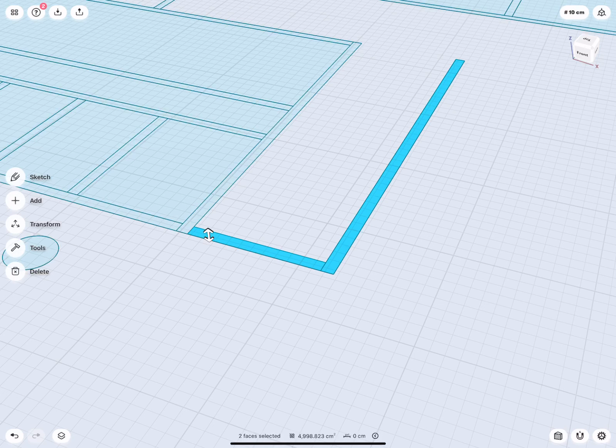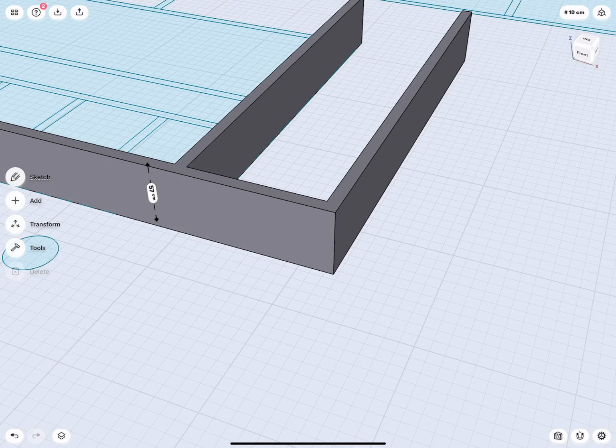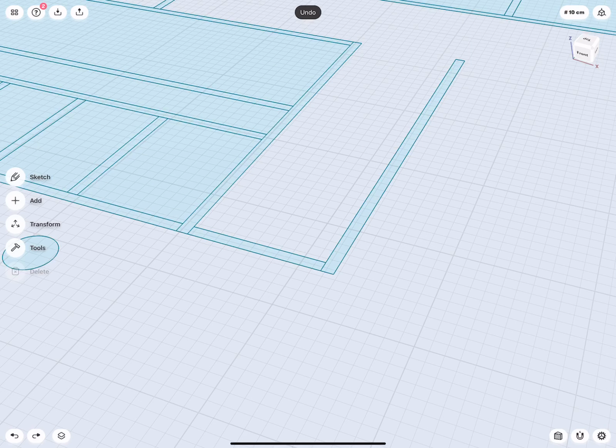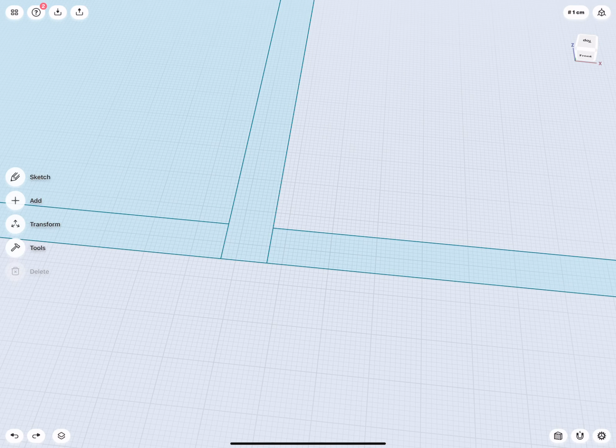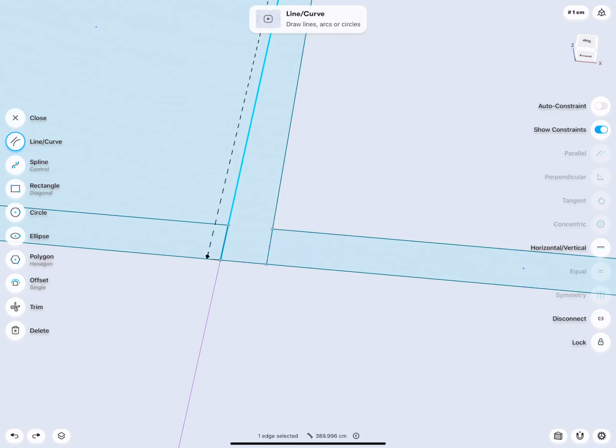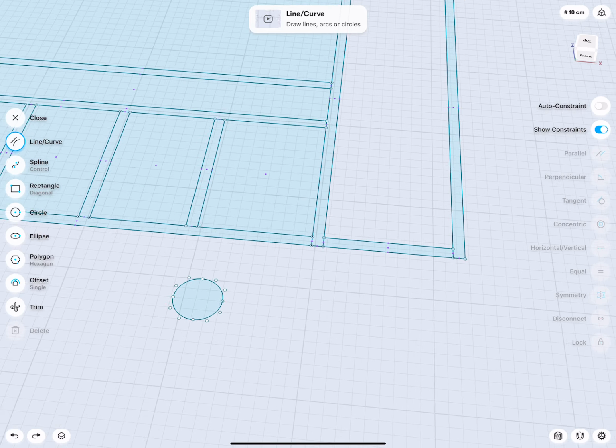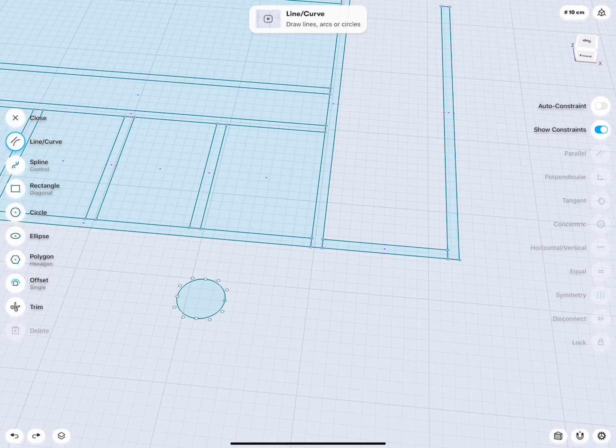These fill areas I can select and, for example, extrude all at once. And you see the three different wall elements are one. So I do not necessarily have to go ahead and remove all these tiny elements which are there in between. This is a matter of preference, the way you would like to work.